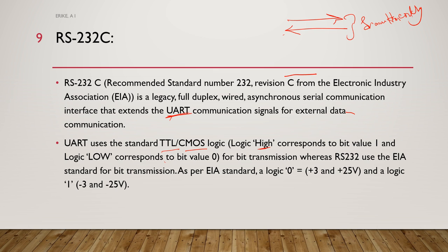In RS232C, the logic follows the EIA standard, so logic 0 is within a certain range of voltage, and whenever there is logic 1, we are looking at getting negative 3 volts to negative 25 volts.